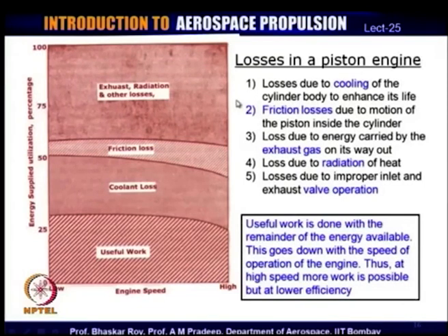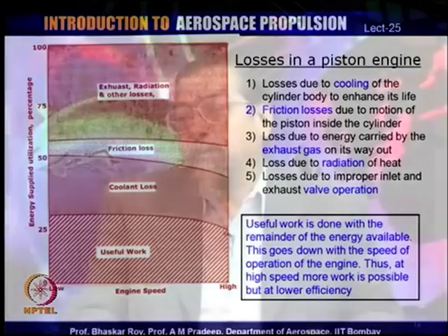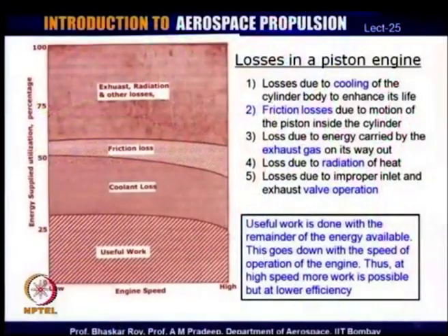Now, you see the cylinder is getting heated, we are burning fuel, the cylinder is getting heated, the piston is getting heated, and they get heated to very high temperature. In spite of the advancement of material science and metallurgy, the heat bearing capacity of these metal bodies has certain limitations, and if you have to provide them with a certain lifespan, which is often in terms of thousands of operational hours, then it is necessary that these bodies are cooled on a continuous basis to lend them a respectable amount of life.